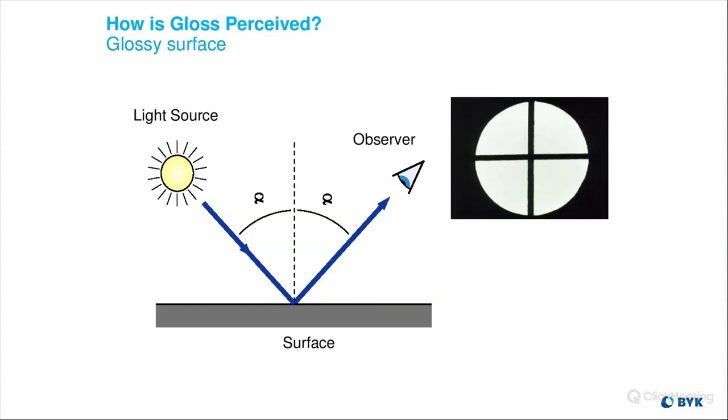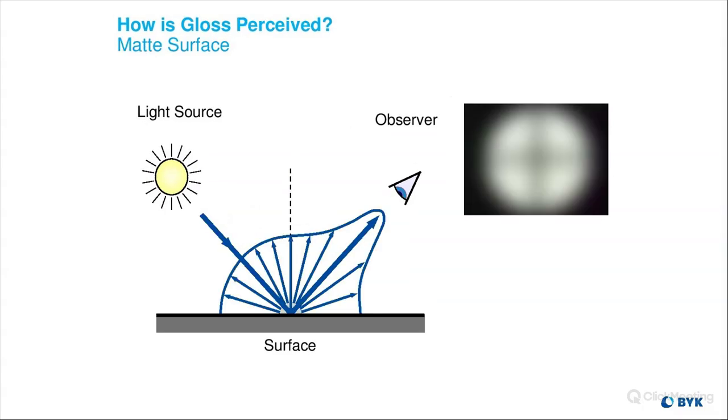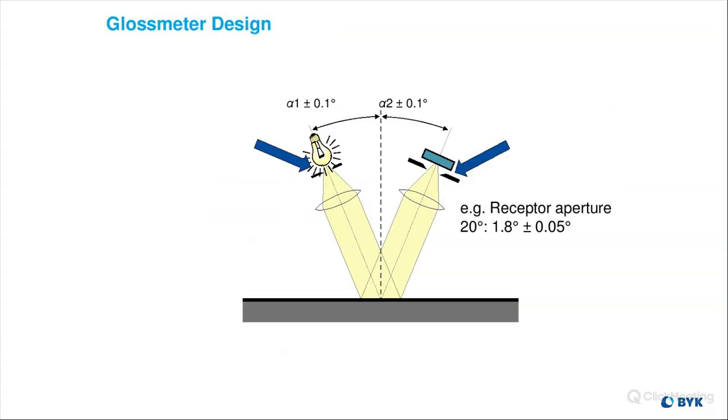If we evaluate a glossy polished surface, the image forming quality is clear, and we say it has good DOI, or good distinctness of image. On the other hand, if we're evaluating a surface that may have some micro scratches, or it's matte, then we're losing a lot of that energy going back to the observer. We're getting that scattering of light, so that distinctness of image is now blurred instead of being crisp and clean, just like when you're measuring over a glossy surface.